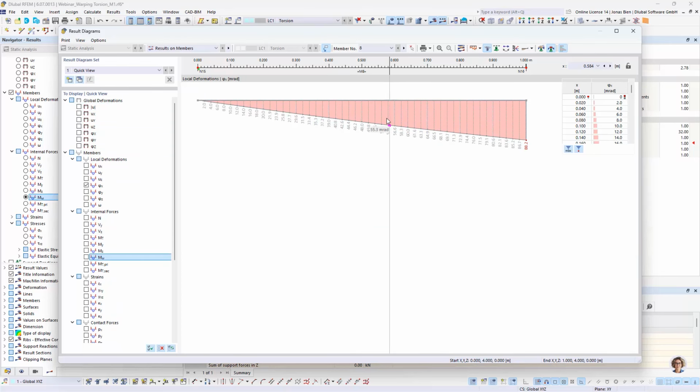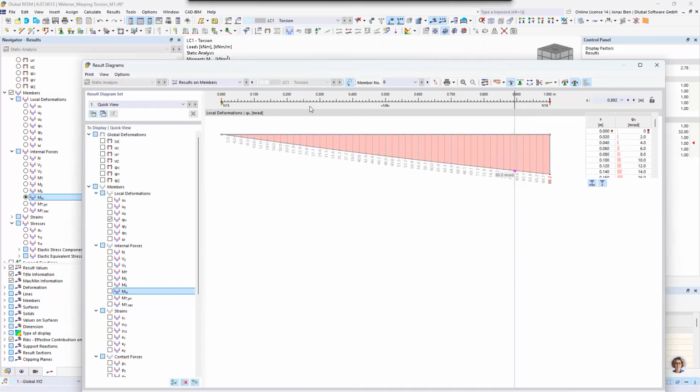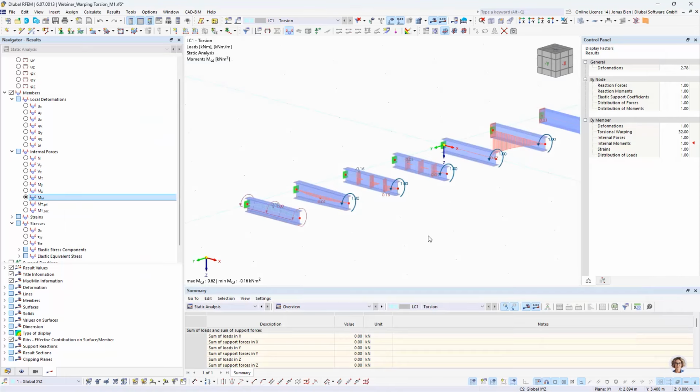but if we check, for example, the value at the end for this configuration here with a uniform moment load along the member length, we see that at the end we have a rotation of 88.2, and at the middle it's not half of it, but it's 84, more or less, or 84.1. So that's not actually half of 88.2, and that means that the derivative of this function cannot be constant. So the twist will not be constant here in this case. All right.